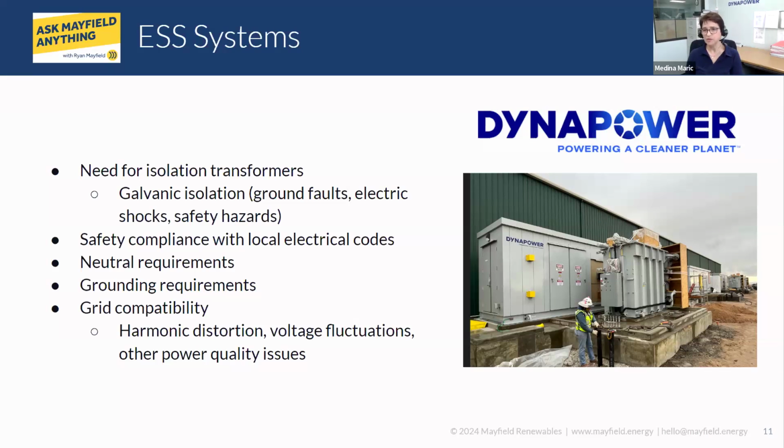Something similar that you see in the picture, this was actually a 54,000 amps rectifier IGBT system, 12 pulse, and the transformer on the front is an oil field transformer with forced oil cooling.